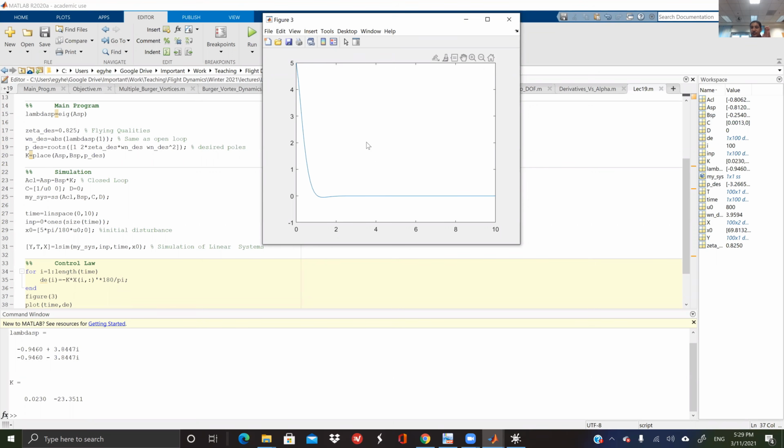Because there is a mechanical constraint on it. So if you required here 30 degrees and the maximum was 25 degrees, then your servo will give only the 25, which means that you will not give the required elevator deflection for the good performance. So you will depart from the good flying qualities that you desired your flight controller for.